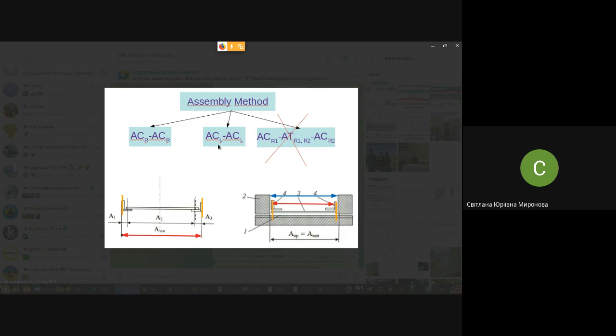It's possible to draw it by a template made of wood or metal or plastic, whatever, any hard material, stiff enough. Also, it's possible to use a photocopy of a template, a so-called photo template. Of course, it extends the manufacturing process and makes it a little more expensive, but it's much faster anyway and has fewer mistakes than manual drawing.